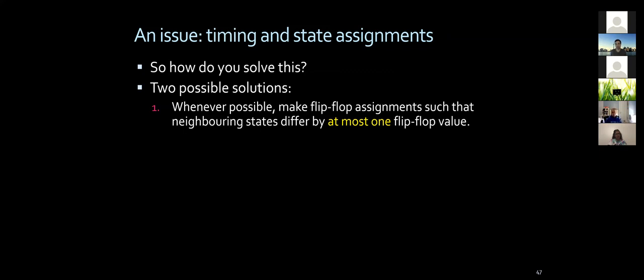So we make sure that everything flips just one way. You can fairly ask me, oh, it's not always possible. And you would be right, assuming that I'm using the same number of flip-flops. But if I use extra flip-flops, then I'm going to get some extra states. So for example, for 3 bits, for 8 states, when I use 3 flip-flops, every state is used. There is no way to get from all zeros to all ones, always flipping just 1 bit. You can try this as an exercise if you want.